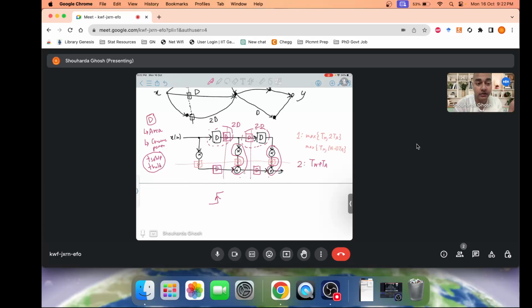Especially in real life integrated circuits, there are clock skews. These clocks are sent by metal wires, so based on the metal wire length you have corresponding delays associated. There's an entire area of work on how you distribute your clock.